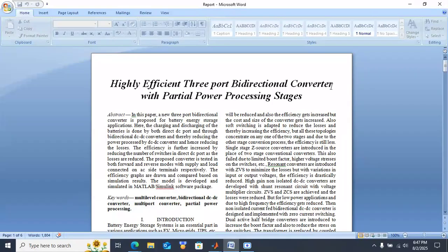And in discharging operation also, when the reference voltage is lower than the battery voltage, the battery will provide the energy directly, and if the reference voltage becomes higher than the battery voltage, at that time the battery will provide the power through boost operation.